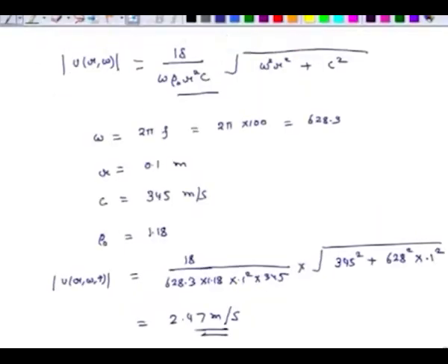Of course, once I am very far out in the far field, the impedance offered by a radial wave is more or less the same as that of a planar wave. So, things start becoming more like planar waves, but when we are fairly close to the source, the impedance offered by a spherical wave is significantly different than that offered by a planar wave.